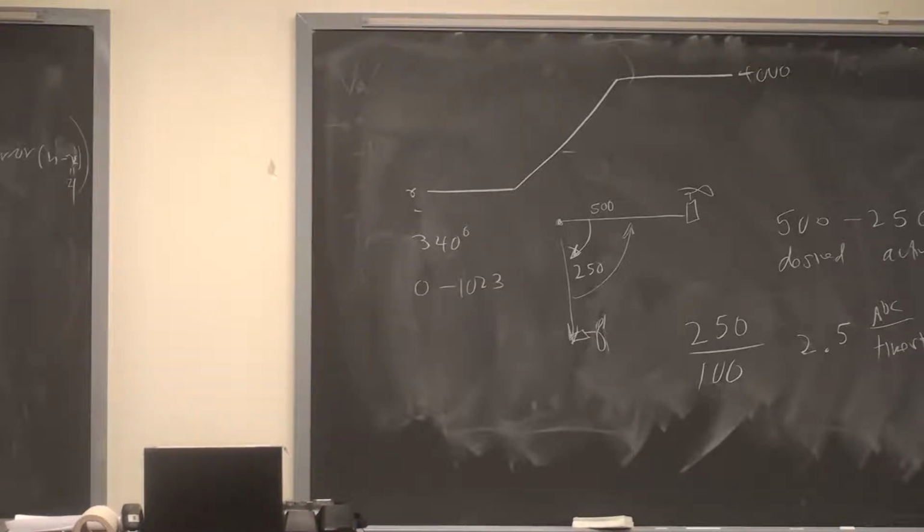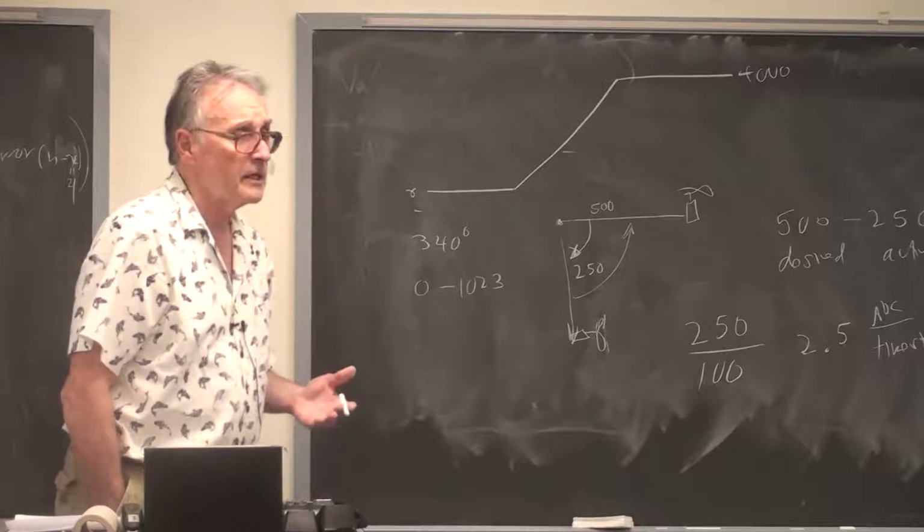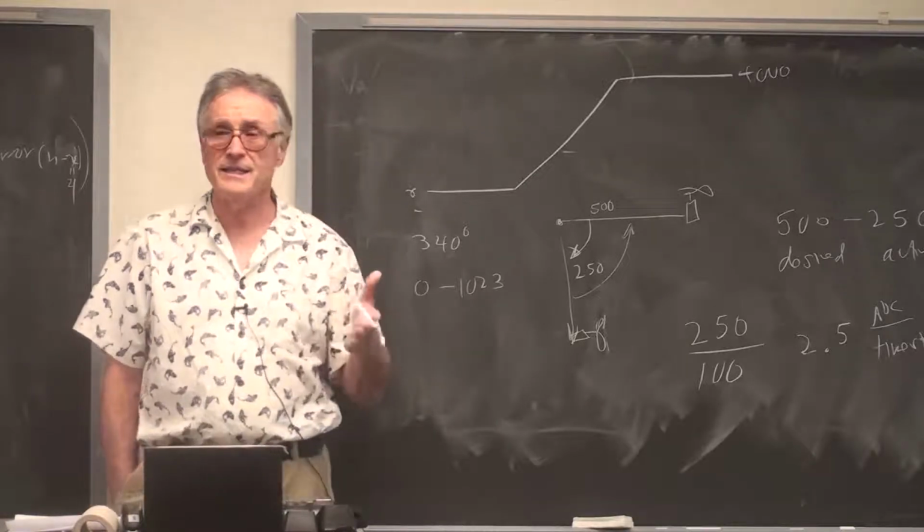So you're going to scale the numbers, assuming you're using ADC units. Let's say that instead of using ADC units, you decide to calculate everything in radians. Now, you're going to have to use fixed point arithmetic. So I suggest doing all of the calculations in raw ADC units.